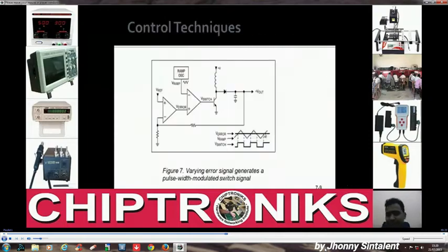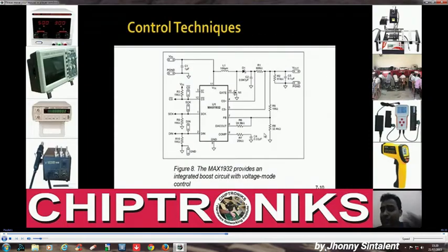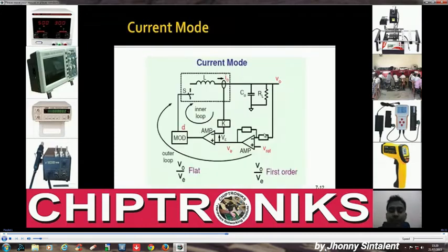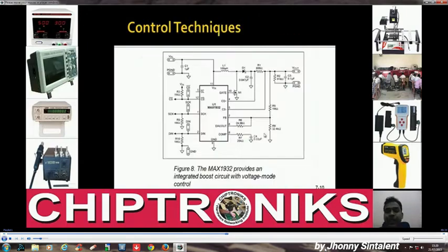that it's not necessary to understand this thing, but if you understand each and every pin, it would be really very good. So what exactly is COMP? COMP is basically generating the feedback voltage, that is the voltage which is sensed over here, which is compared with an internal comparator having a reference voltage of 1.25.